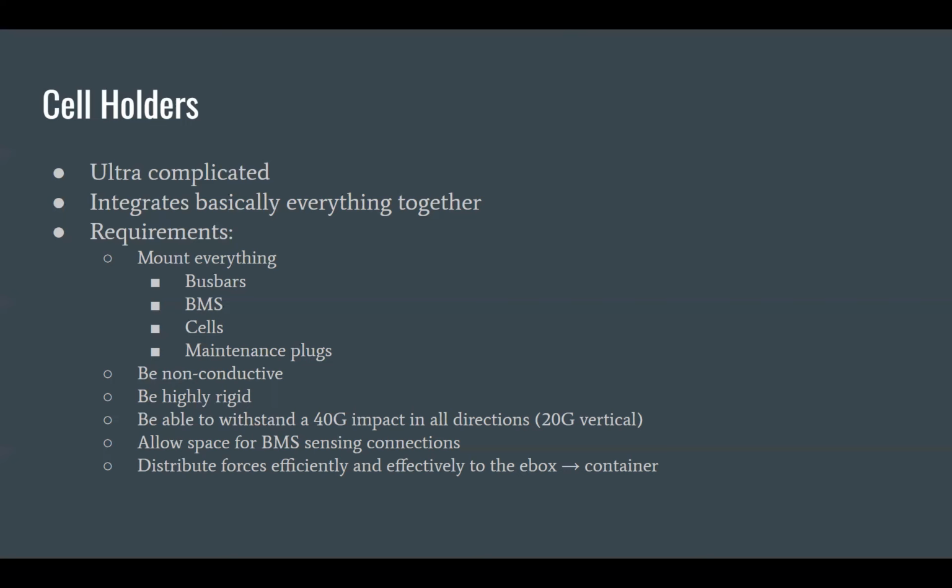So that's why we usually print and manufacture them out of plastic of some sort. But the issue is that, like we talked about, there are all these great properties that come along with bonding your battery cells. But because we're bonding them, all those bonds are formed ultrasonically, which means your battery cell holders need to be very rigid. So the thing that holds everything also now has to be made of these way harder to print, more complex materials that have glass content or potentially a high carbon fiber content. That's why, for example, this year all of our cell holders have been highly rigid, but they are a glass filled plastic. So they're non-conductive, but they're still very rigid.